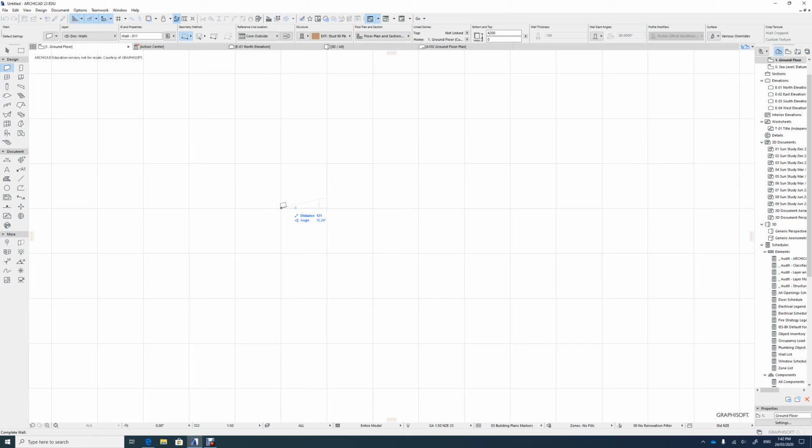So if I click on the grid and go X on my keyboard, it's going to bring up that X coordinate. And then we go, say, 6,000, which is 6 meters. And then we press Shift plus. Shift plus is to tell it to go right. My wall's not quite straight there. Oh well, anyway, we can do that again. And click Enter. Probably wasn't straight because when I started. So when you click and let go of your mouse, just make sure that that little black pen there stays black and isn't white. So let's do that again.